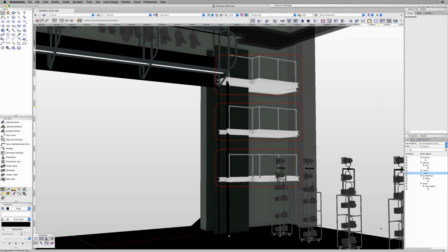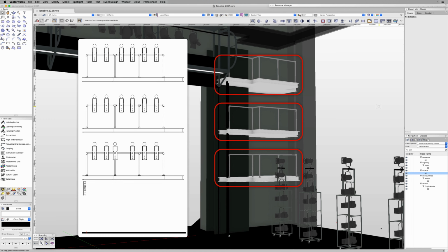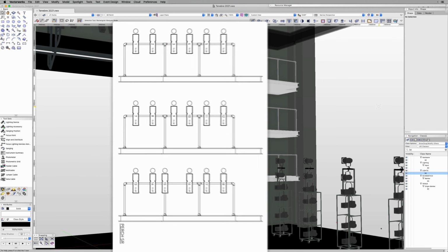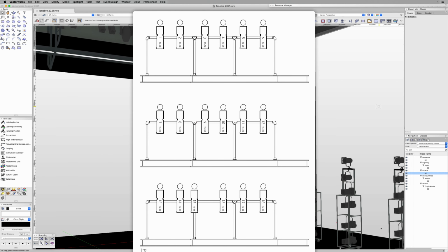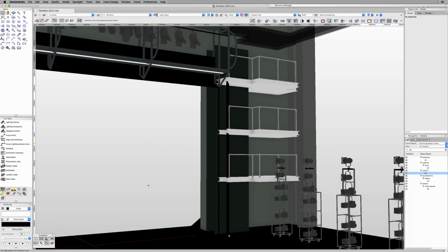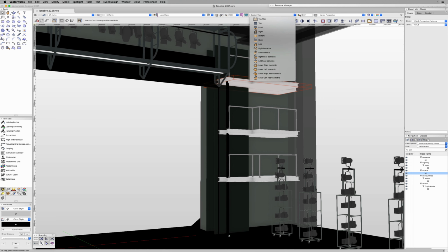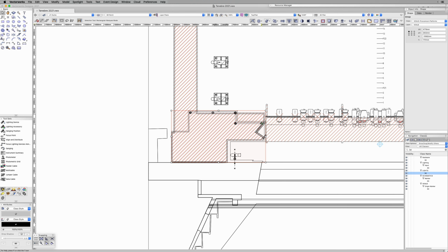I want to load these perch positions with lighting equipment and have each side of the proscenium report the lights to a schematic view, whilst at the same time seeing the geometry of the 3 levels. The process that I've come up with involves creating a section viewport. So I go to a top plan view of the area I want to section. There are 2 or 3 ways to do this, but by far the most interactive is to use the clip cube.